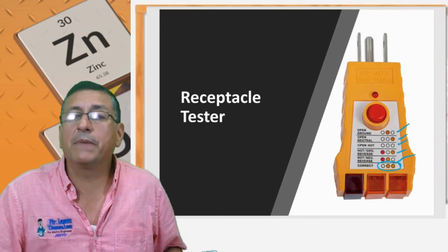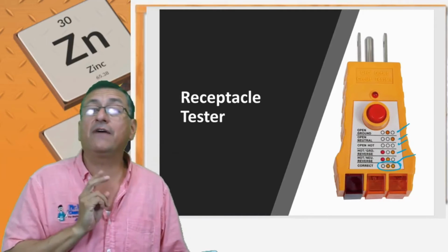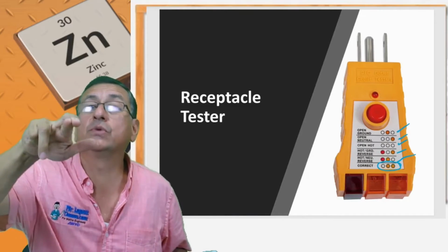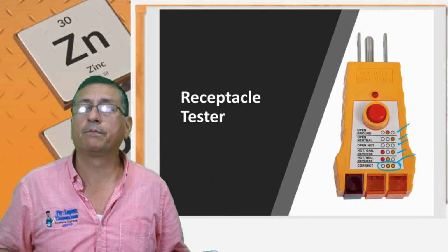This is important. Periodically check all the outlets in your boat, and verify if you have an outlet with switched connection and fix it immediately.